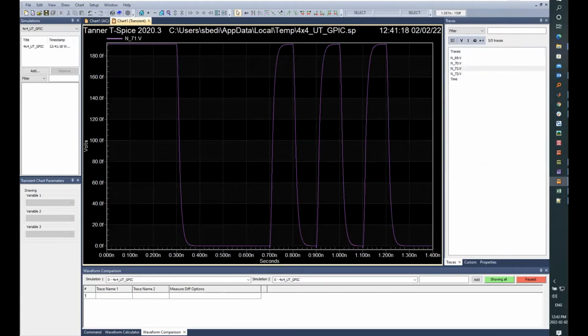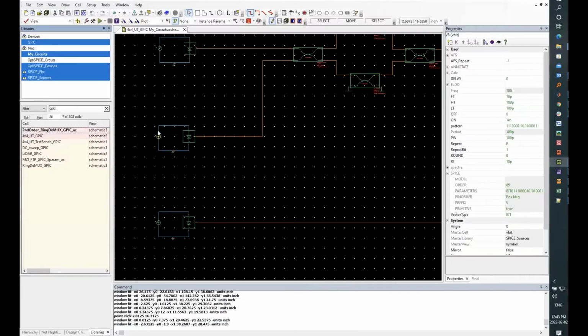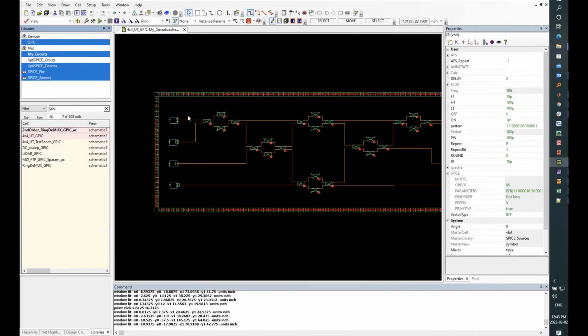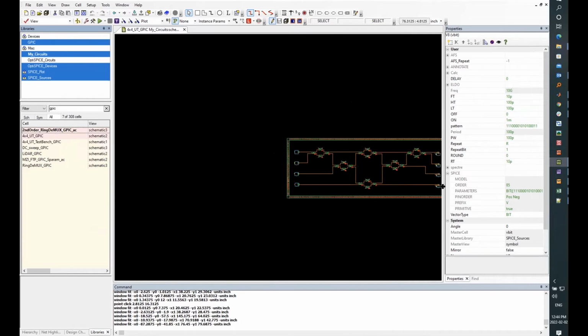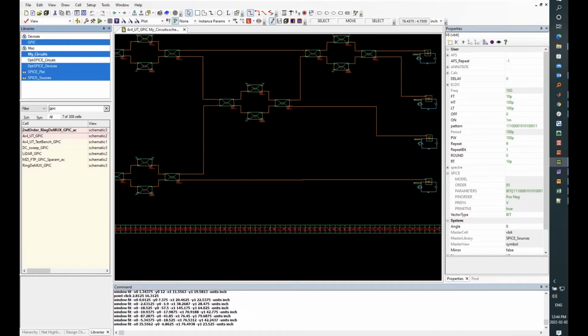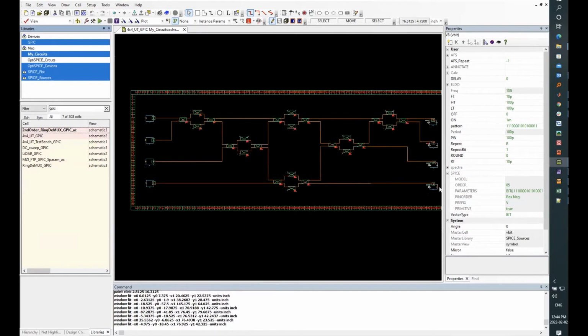So you can see that channel 2 is being obtained at output 3, and the same goes for the rest of the channels. So this shows how each frequency channel is transferring from one stage to the second stage to the third stage, and then all the way out. So this is a waveguide mesh unitary transformer. So yeah, that's an example for the AC simulation.